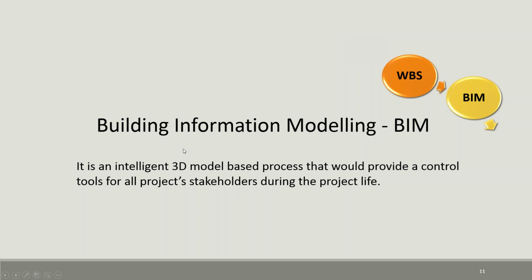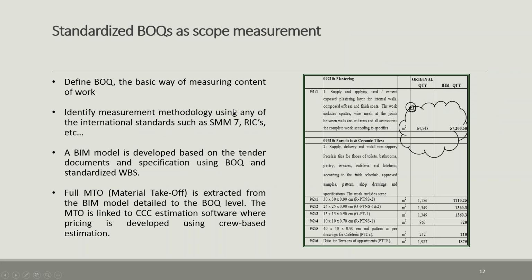So we decided at the beginning, since we are doing a 3D model, we want to use it to measure the scope of the work. So when we build a 3D model, we also build a takeoff of all the quantities we need to build so that we finish that model. So basically, we are building, for example, a foundation. We have 3 activities we need to do: formwork, rebar, and concrete.